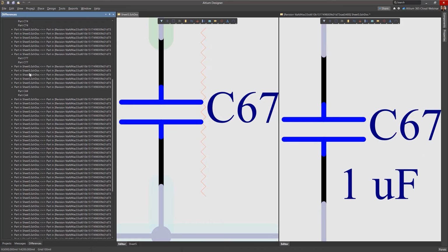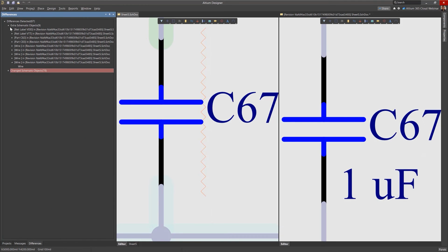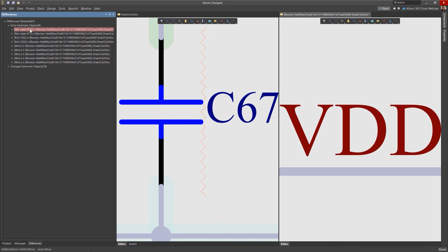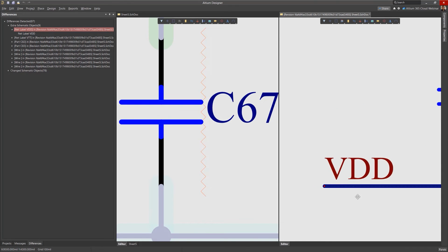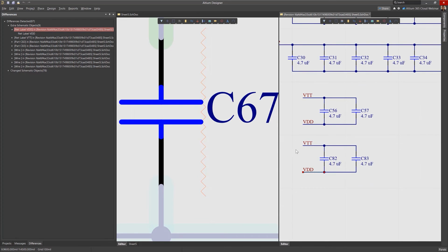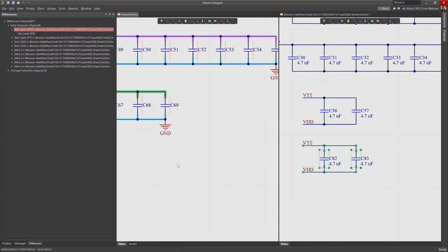If you need to track down any issues that have been introduced, it also categorizes them by type. So here we have extra schematic items. So we can come through here and you see that these are the extra schematic items, right? Because I copy pasted this whole area. So this has been added in, and it will obviously not be found in this revision.